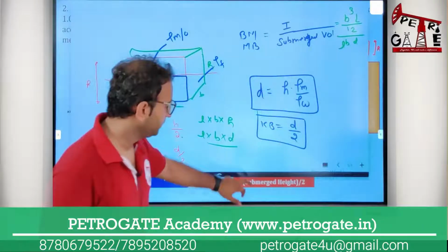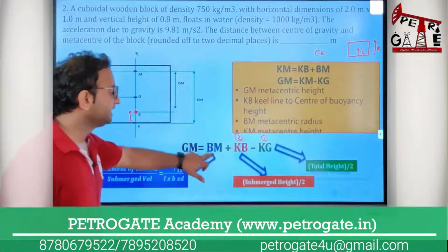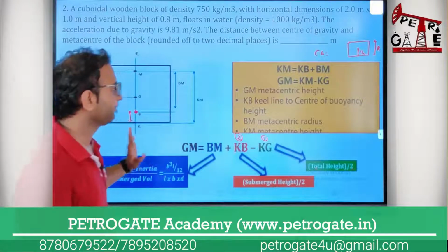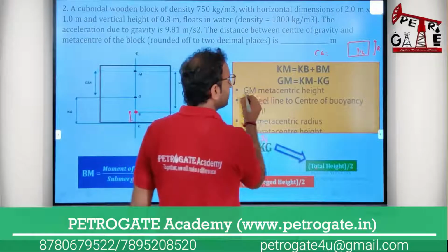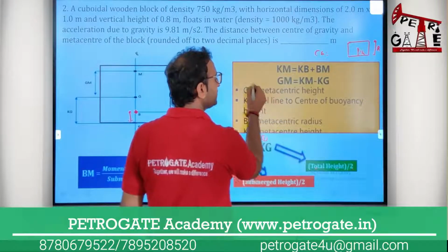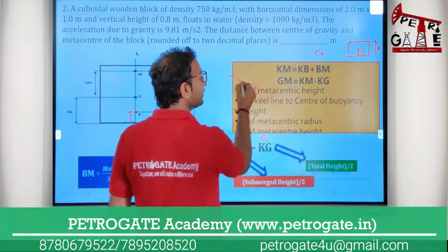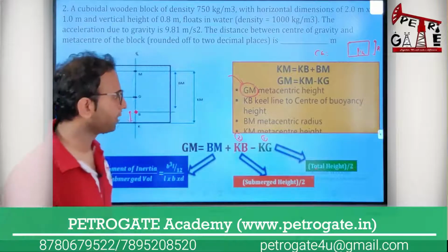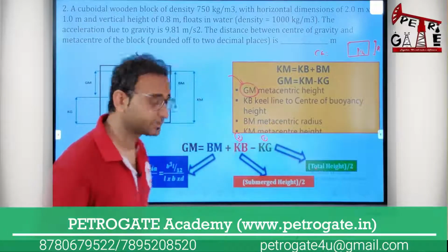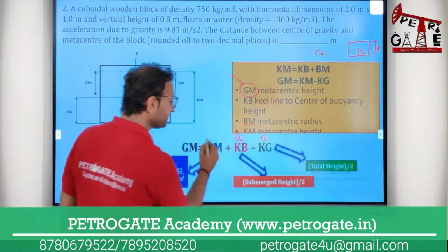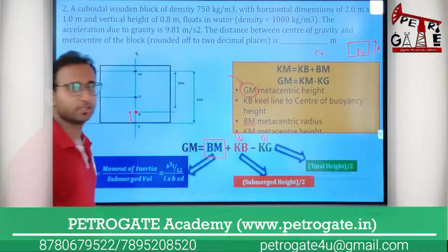Okay, no problem. So now if I'm getting this, you will get GM. If the question is, sir, how to calculate metacentric height, you will calculate GM. If he is given directly to calculate GM, you will calculate GM, no problem. If he is asking to calculate metacentric radius, metacentric radius is BM.